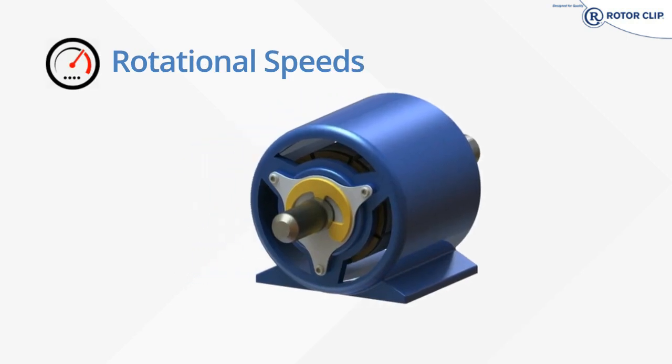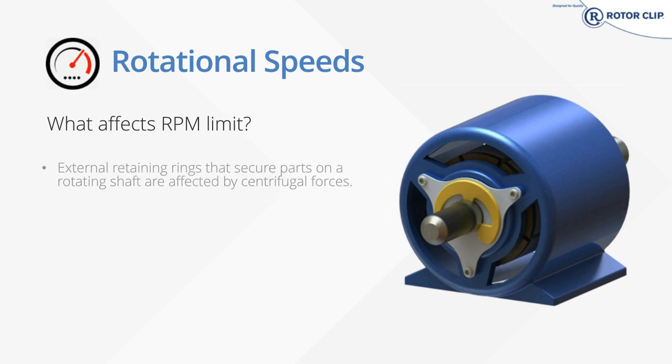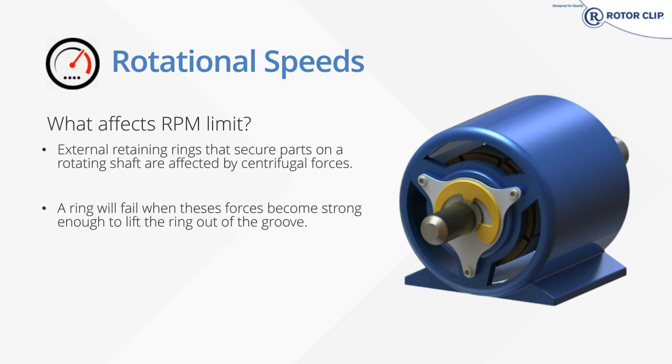The first design challenge that you may come across is rotational speeds. If you have a fast-moving motor or some other fast-moving shaft, you'll need to consider the speeds that you're putting on the ring. This is only a concern with external rings because if you have a ring in a housing, as the speeds increase, the ring just wants to push further and further into that groove. So, picture yourself on a gravitron at a carnival, and you'll see the rings aren't going anywhere. But on the external side, you do have to worry about this.